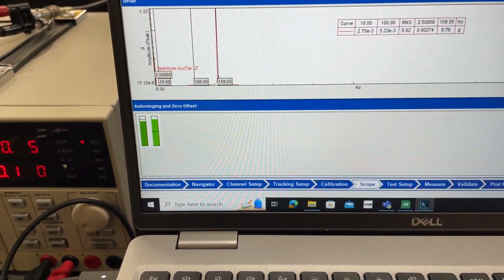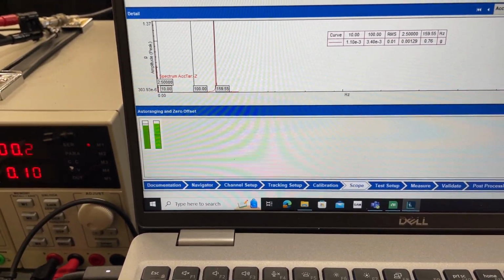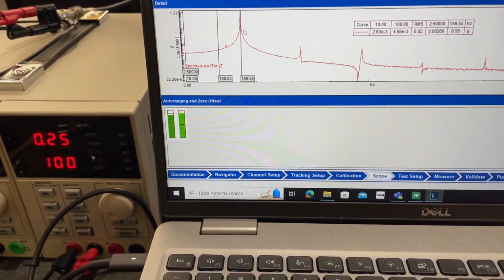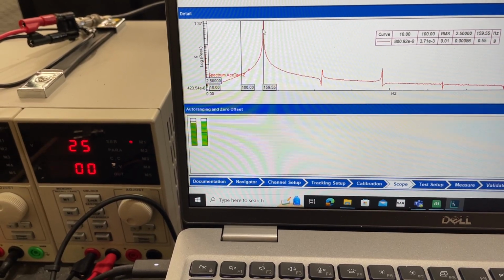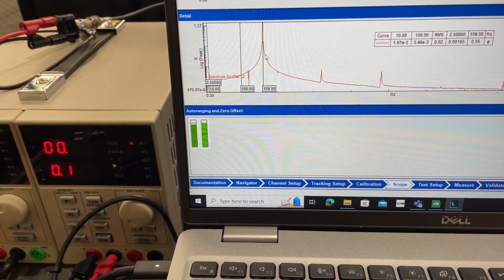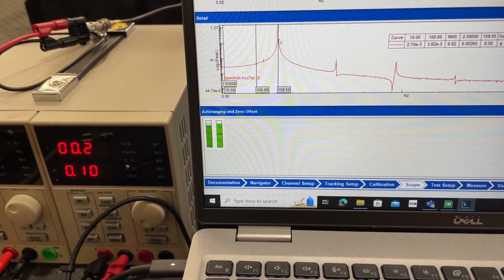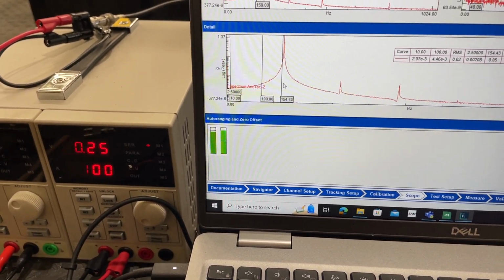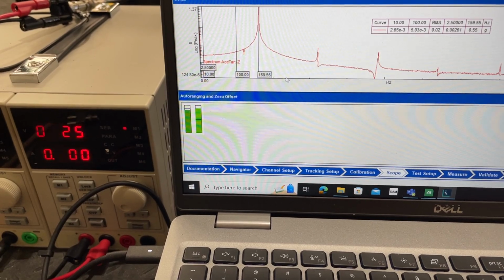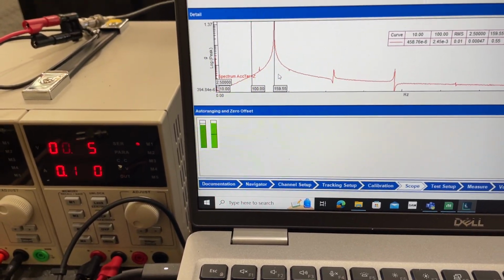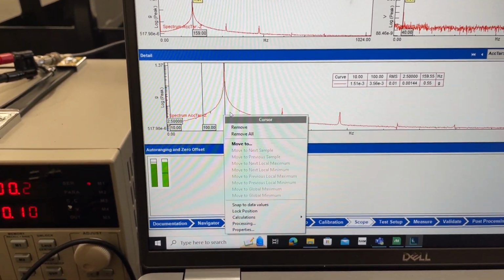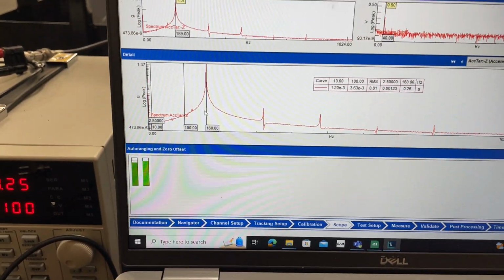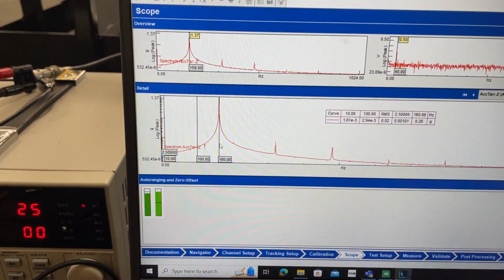I can look at that also in frequency domain. It's currently sitting on the accelerometer calibrator, which is producing 159.2 Hertz sine wave, and you can see that the behavior of the accelerometer is as expected. We have a very dominant peak at 159.2 Hertz. These cursors are not yet snapping to data values. We've got 1 Hertz resolution, so the closest I can get is 159 Hertz.